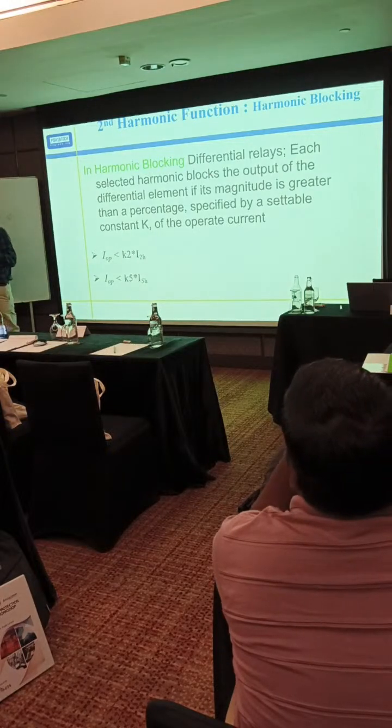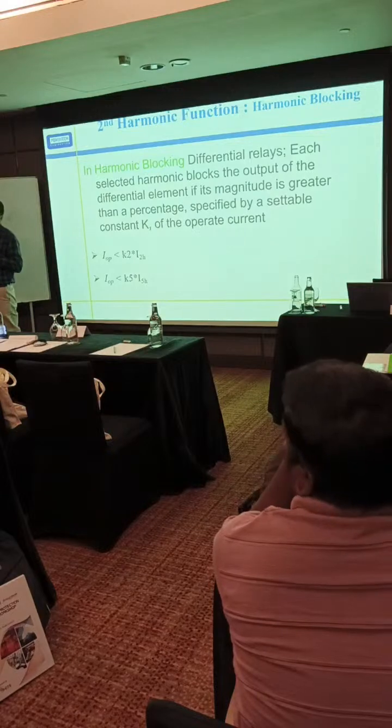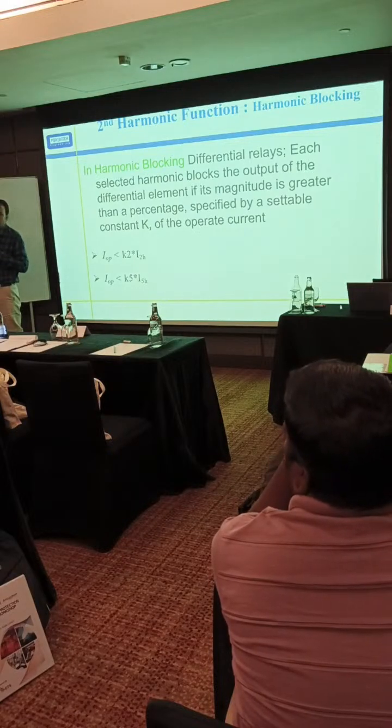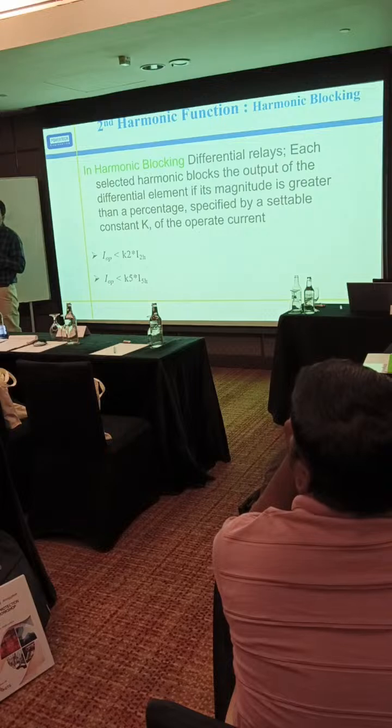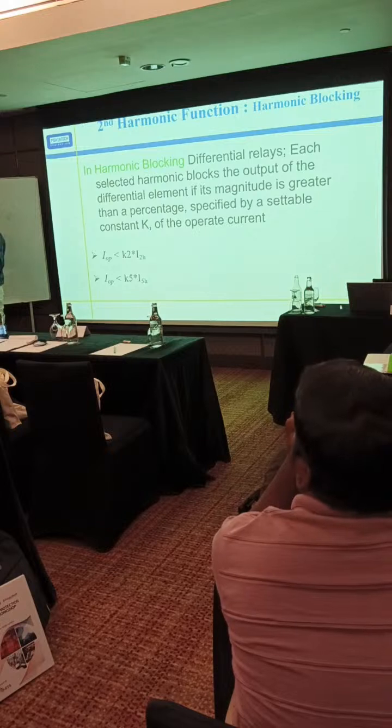If you have to do the harmonic test, then what will we do? We inject the fundamental current and harmonic current, and we reduce the harmonic current from, suppose, 50% of the harmonic current. Simply understand, 1 ampere is the fundamental current, and the setting is let us say 20%.